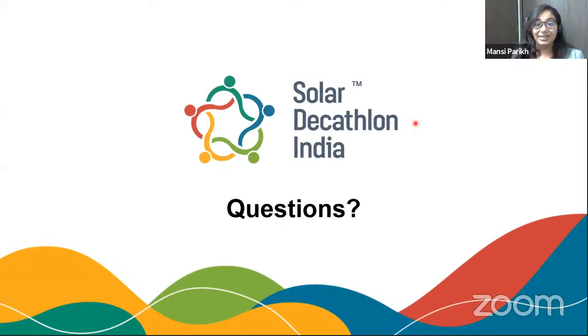I would believe yes, because as I showed in the irradiation analysis, the amount of shading which you would be requiring in north would be very much different as compared to what you would require in south. It depends on the kind of spaces you have. It would be very project specific. But one thing I can be sure of is it is easier to shade windows in north as compared to south. This is more related to the hot climates. So that depends on you. How do you want to proceed? You want to make it difficult or easier for you to shade the windows?